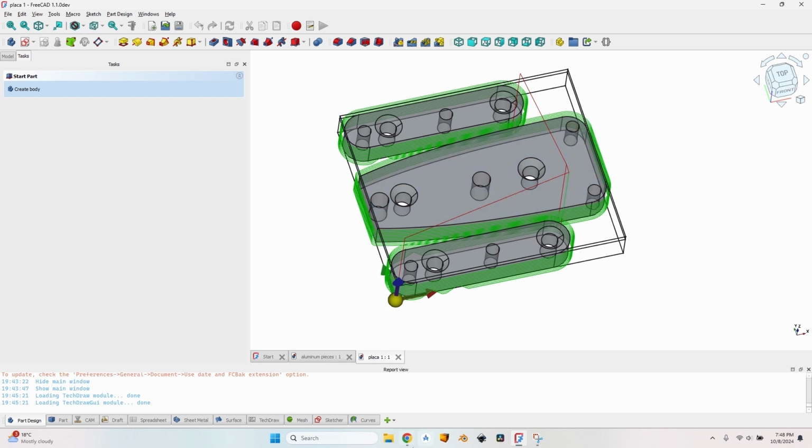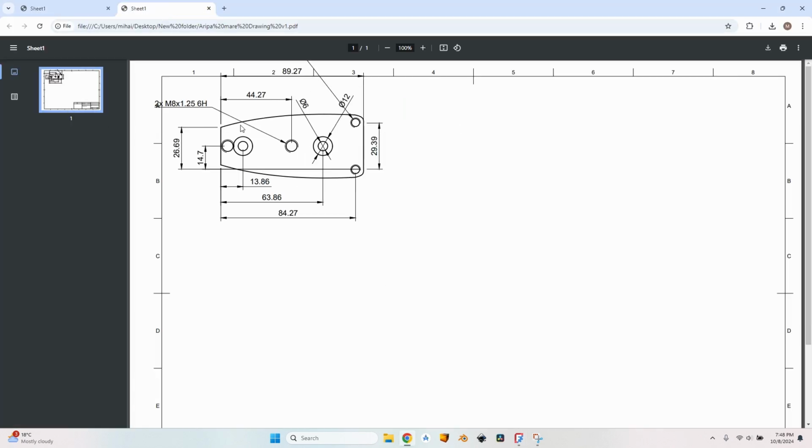They are going to be aluminum. I had these two sketches. Let's transform these two sketches into 3D objects and then generate the G-code, generate the toolpath, go on to the CNC and mill them, drill the holes. The tapping, I won't be doing it on the CNC, I will be doing it by hand, but I will drill the holes before, so it should be very easy.